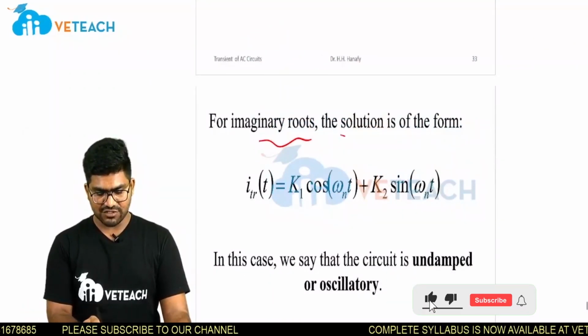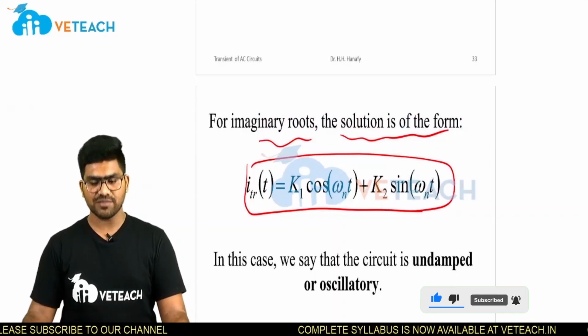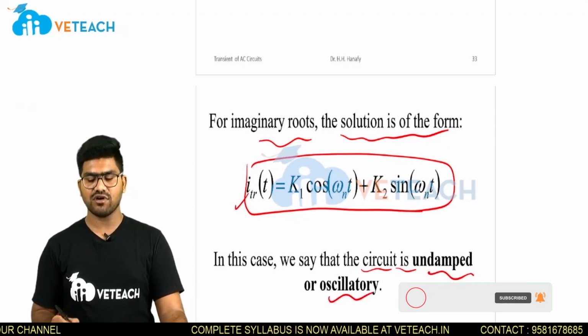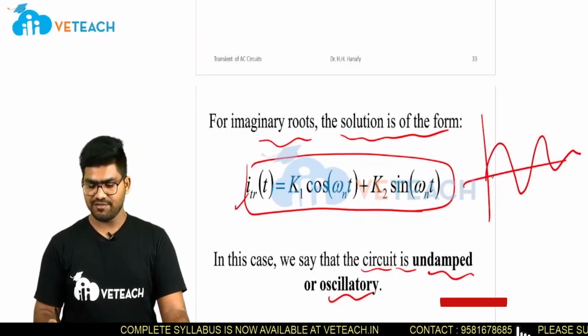So for imaginary roots, the solution is of the form i_tr(t) = k1 cos omega n t + k2 sin omega n t. So in this case, we say that the circuit is undamped or oscillatory also. Undamped or oscillatory means it will be like this. So these are the four cases based upon zeta.